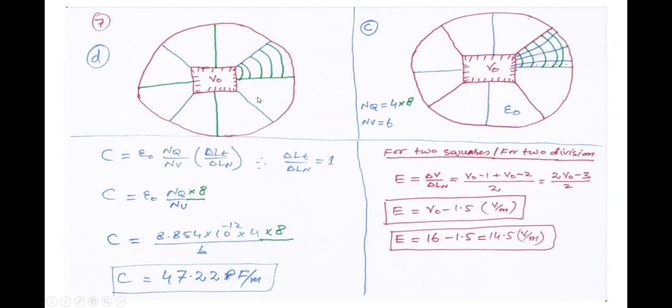Then we divided the space between the inner conductor and outer conductor into 8 big symmetrical flux tubes, and then we further subdivided one of the big flux tubes into sub flux tubes. In this way you can fill the space between the conducting boundaries with a large number of curvilinear squares. This is known as the curvilinear square map method.